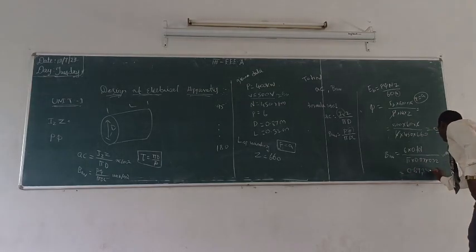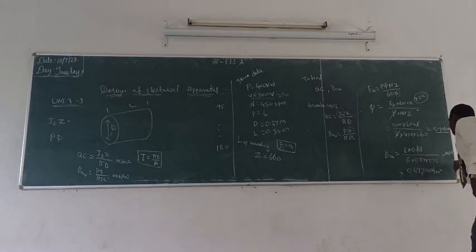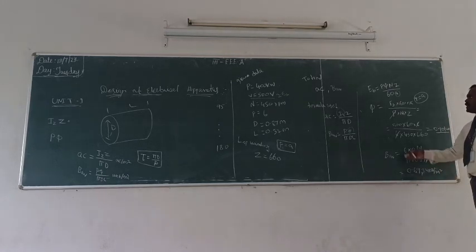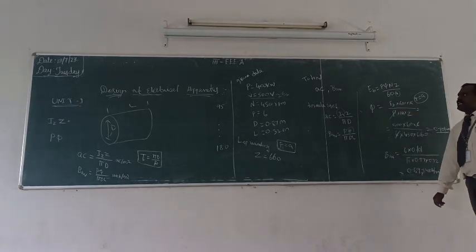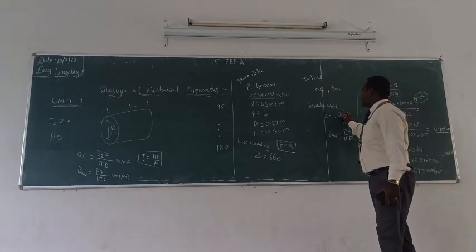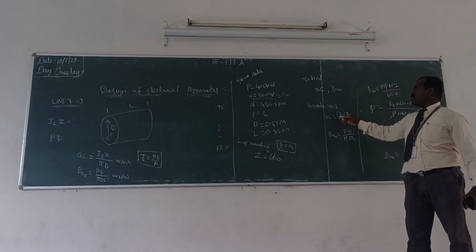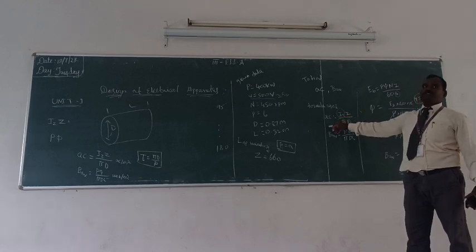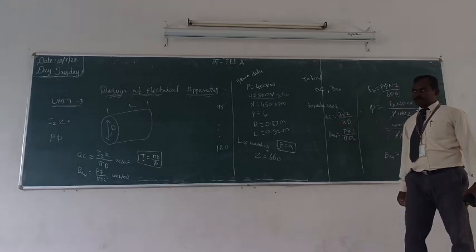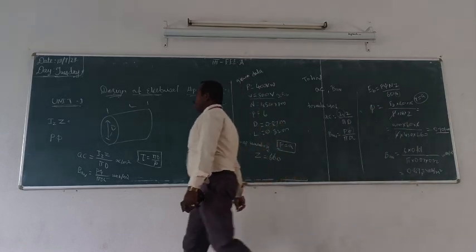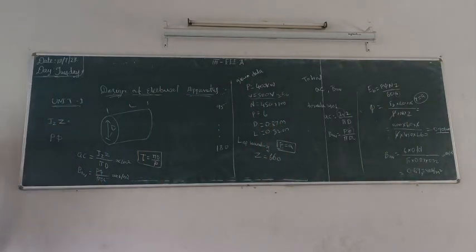0.693 Weber per meter square, right? That is the BAV. Similarly, you need to find the IZ first. Then you can substitute the IZ value and the remaining values in the equation, and then you can find the ampere conductor, right? So how can you find the IZ value?